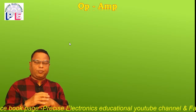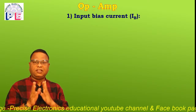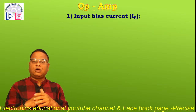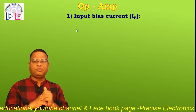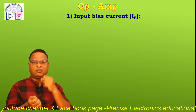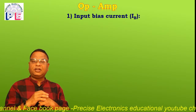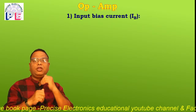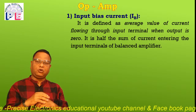The parameters of op-amp. The first parameter is input bias current, that is I suffix B, I for current and B for bias current. It is sometimes given as IB. What is input bias current? It is defined as the average value of current flowing through the input terminals of the op-amp when the output is 0.